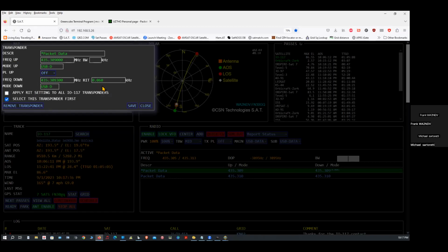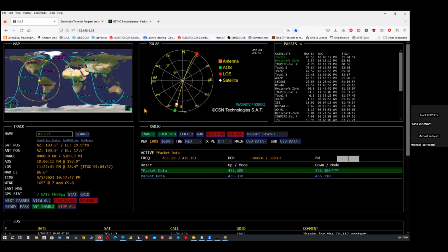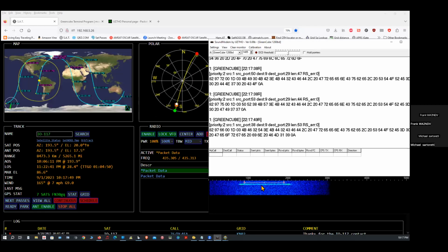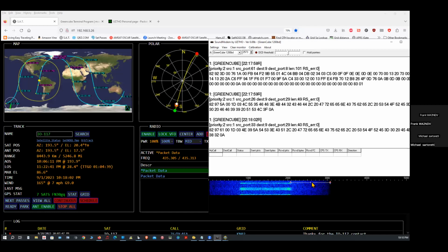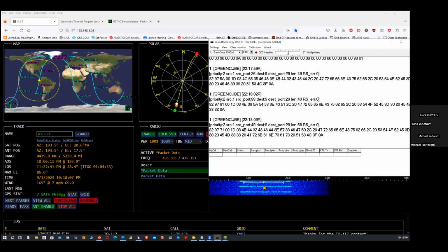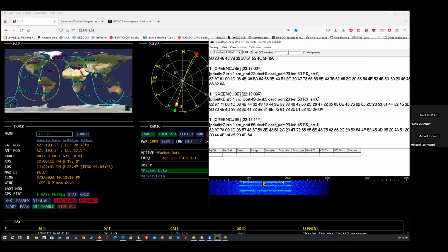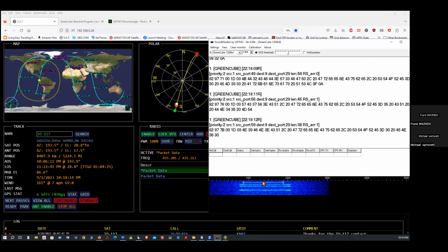It's tricky to dial this in. Some rigs are different. Some rigs are a little bit off frequency from one another. You know, this is 60 hertz. You're going to have to finesse it a little bit. The idea is to get the downlink, the soundmodem signal here, the download frequency, starting at about 800 here and going to about 2100. And then you must move this bar to cover most of it. And when you do, your receive will start receiving and your transmit will attempt to get into the satellite.